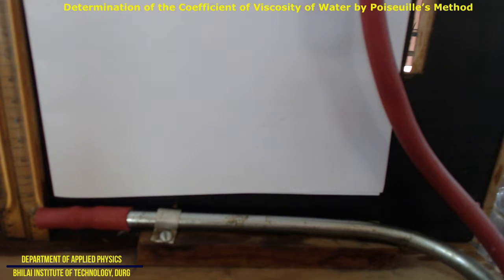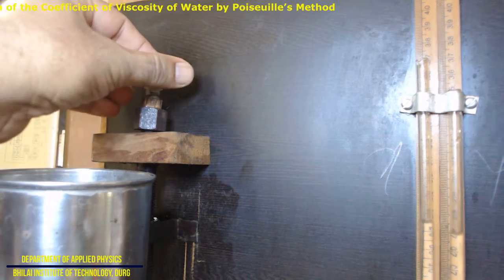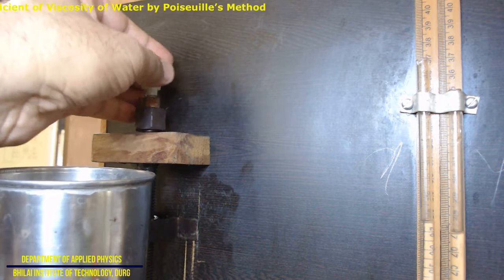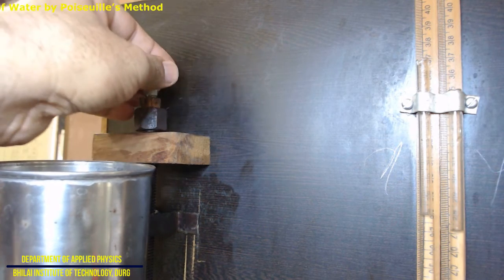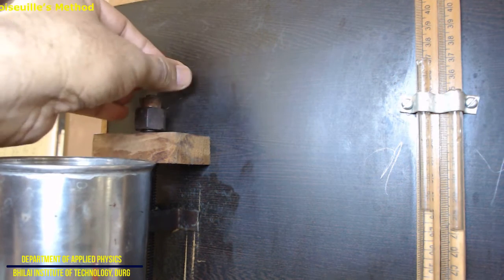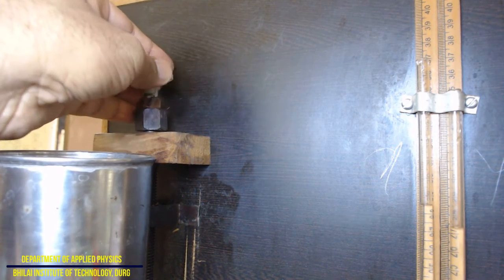Now to take the second reading, what we have to do, I am going to explain to you. Again we are going to rotate this screw in such a way that the level of the water in the left arm is going to increase. You can see slowly the level is increasing, and we are going to make this level equal to 28 centimeter. Slowly, see, we have crossed 27.5, and this is 28 centimeter.